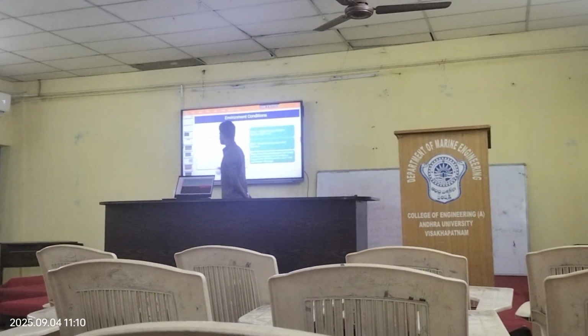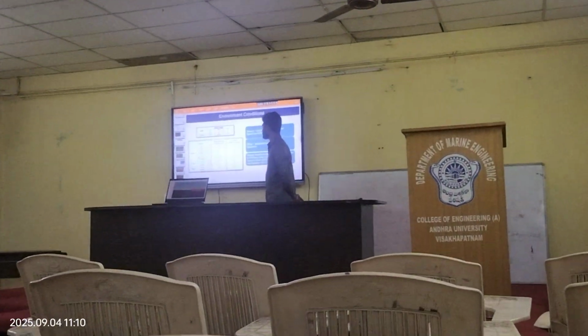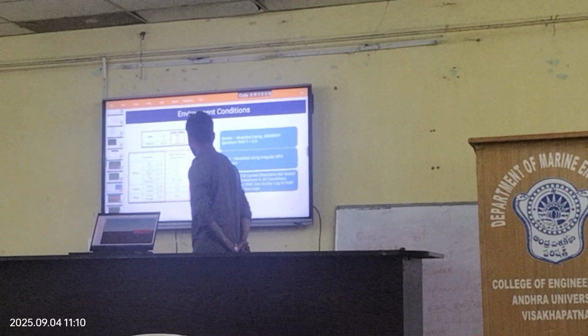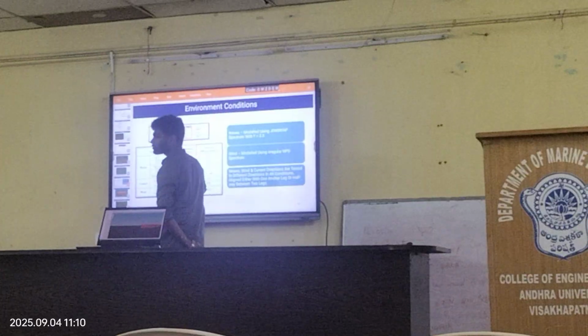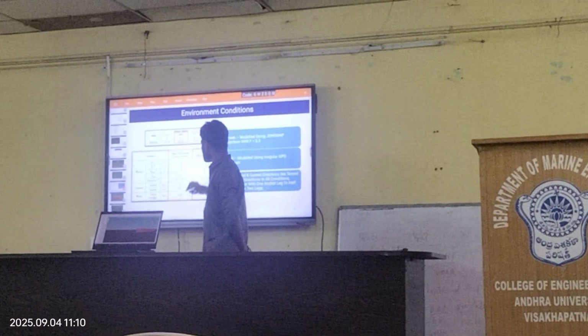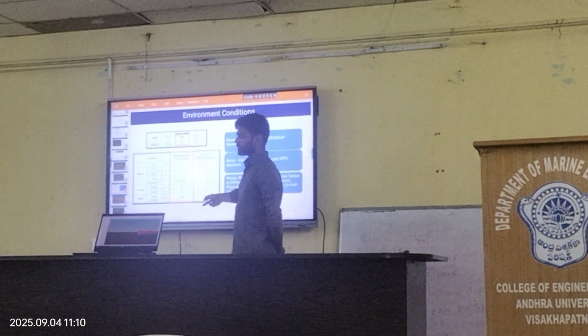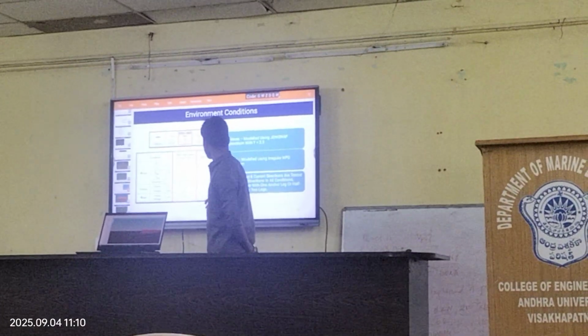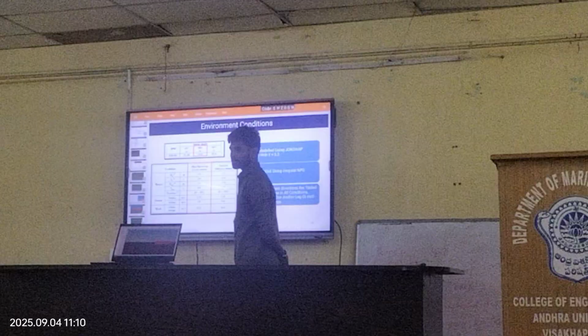And the environment conditions used are these: the mean sea level water depth of 37.9 meters is used, and the maximum operating storm, a 1 year storm, parameters are used. The survival condition I haven't conducted. This is used for the fatigue phenomenon, but because of time constraint, I haven't done this.